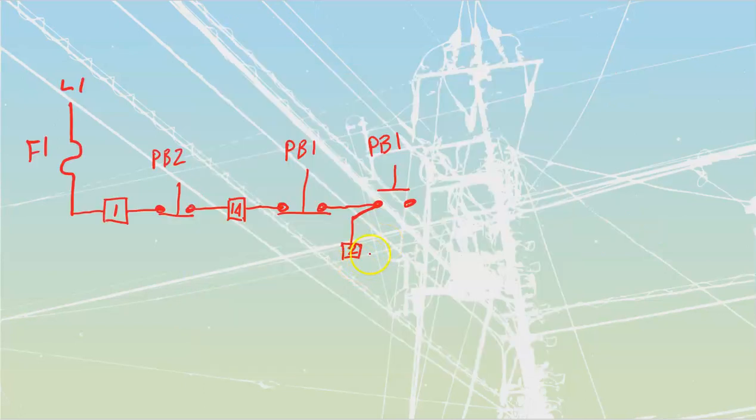So I'm going to take this wire number 2, and I'm going to draw it to an auxiliary contact like that. We've got the opposite side of the auxiliary contact. We still haven't done any connections to it, but we're going to finish up with wire 2. Okay, don't jump ahead. Go on to these ones. You screw yourself up because you forget that you still have unfinished connections inside of here.